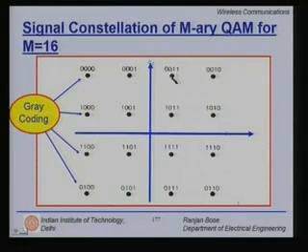If you consider the symbol above, there again we have flipped only one of the bits and we come to 0011 and so on and so forth. On the left you have flipped the third bit only. So, the nearest change, the closest Euclidean distance wise symbol, is also the closest Hamming distance wise separation.